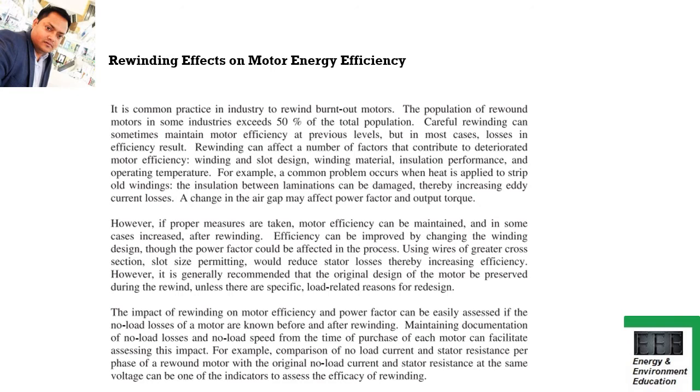It's better to purchase a new energy efficient motor than to stick to motors which have been rewound a number of times. This is the recommendation we give to clients, especially when we go for an energy audit. So this is the major concept that you must understand on this part of the chapter, and you may just go through the chapter. You may understand this part by yourself also. It's not very difficult to understand, so I'm not going to explain it, friends. As far as exams are concerned, you may expect at least one question on this part, as a short answer type question or a part of a long answer type question: the rewinding effects on motor energy efficiency, friends.